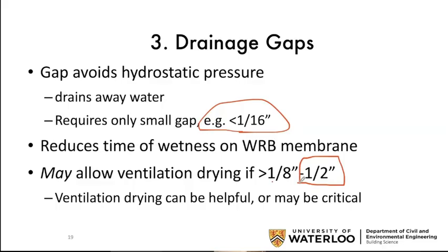And that's why when you see a gap drawing, don't misread it. I mean, it's easy. If you're looking for 80% solutions, then you should say the gap should be more than 12 millimeters and it's a drainage and a ventilation space. But when you're hiring an engineer to make decisions, you kind of have to know more of the story.